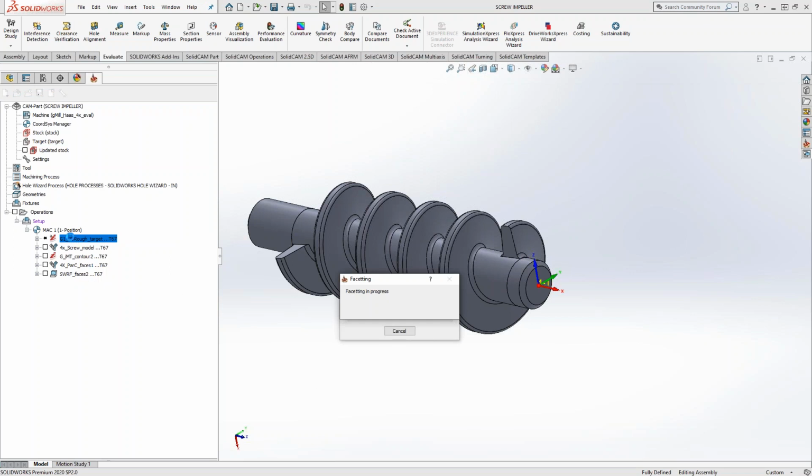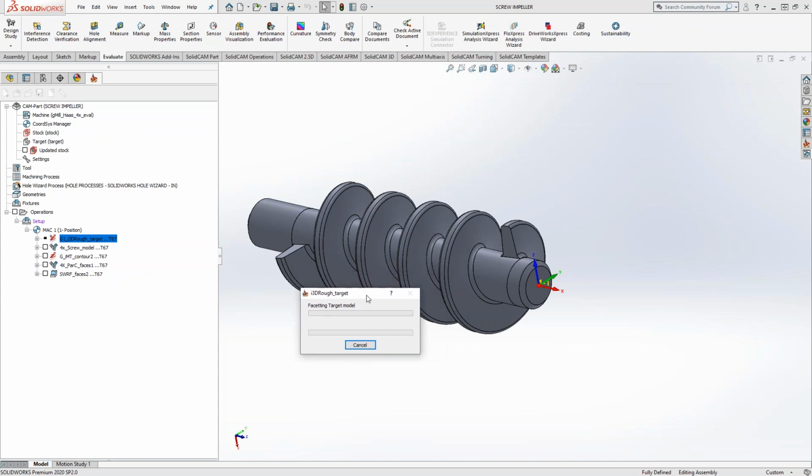And I had to put it at the top of the toolpath list because, again, this is a recognition toolpath. So we want it to recognize all of the stock. If I had put it at the end, there probably wouldn't be any leftover material to machine. Yeah, and that's why we do get a little bit longer calculation times with the feature recognition ones, just because it's going through, looking at the stock, looking at the target model, faceting everything, making sure it's not going to gouge, along with the iMachining algorithm there. And let's make sure it doesn't crash.